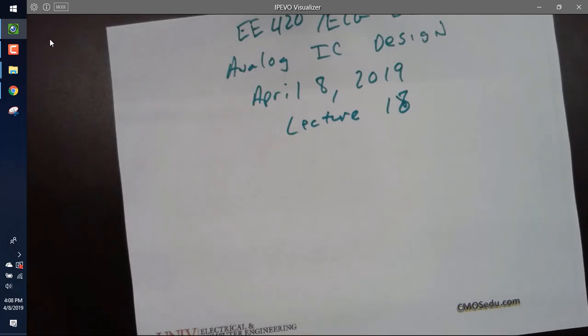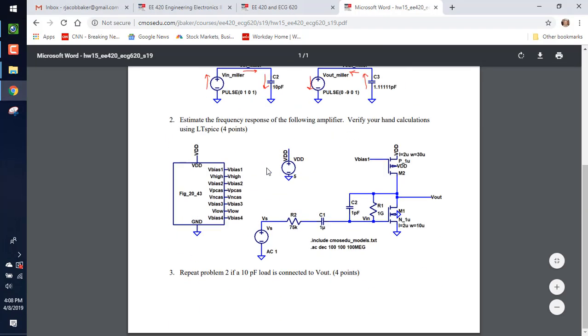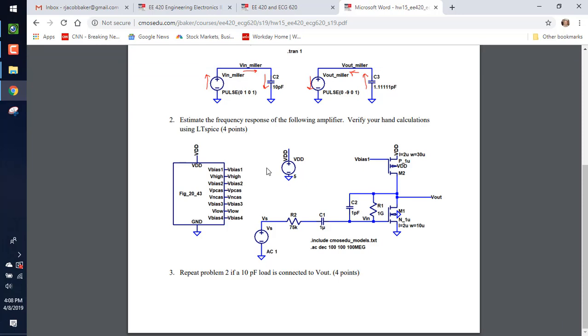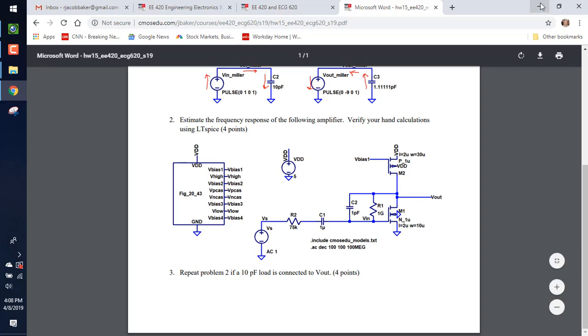Okay, so let's go look at homework 2. And first thing you note, in the pole splitting summary model, the input R1 and GM1 don't coincide to what I have here. So what I'm going to start out doing is I'm going to Nortonize this equivalent circuit. So I'll go back and I say 1 and 75K. And how do I treat the 1 microfarad? It's a short. Open for DC, short for AC. Okay, so we'll start here, 75K and 1.